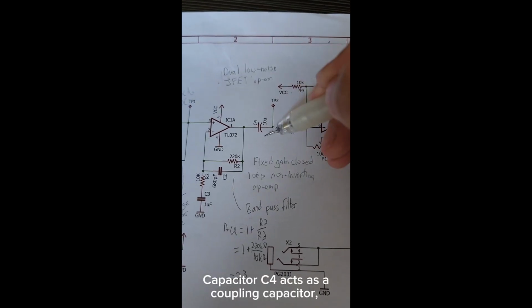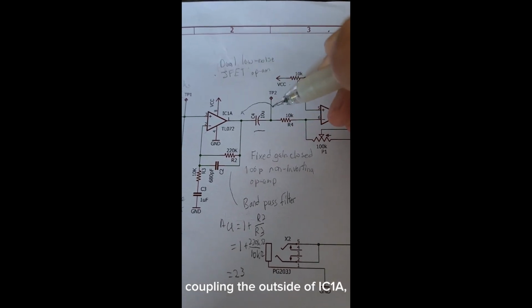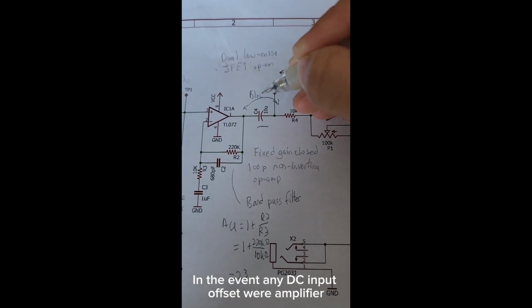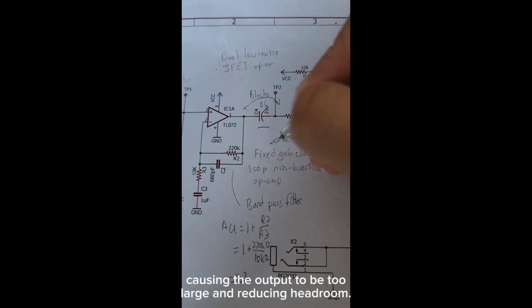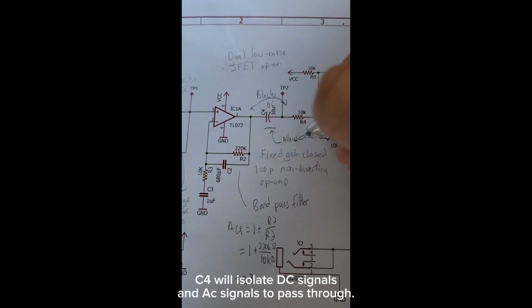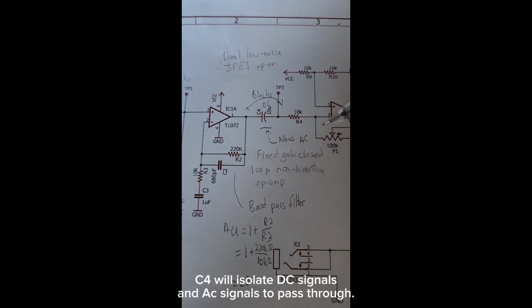Capacitor C4 acts as a coupling capacitor, coupling the output of IC1A, the first op-amp, to the next segment. In the event any DC input offset were amplified, there will be a larger output offset, causing the output to be too large and reducing headroom. This causes the output waveform to be cut. C4 will isolate DC signals and allow AC signals to pass through.